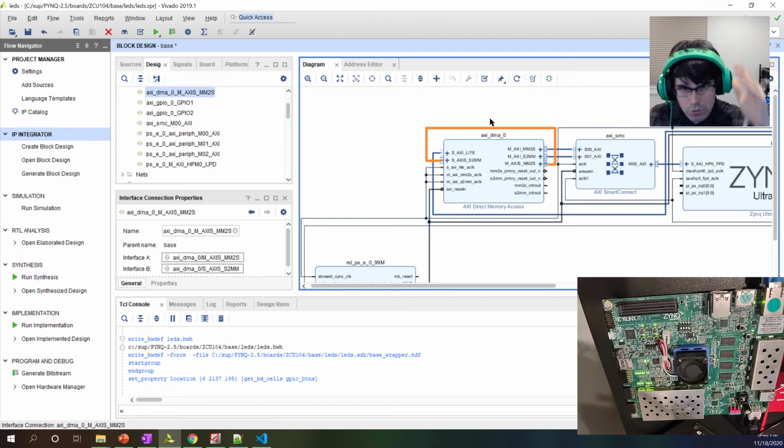And our goal is we're going to drop an HLS core right here. That's going to have an AXI stream in and an AXI stream out, and it's going to have an AXI-Light interface. Probably the first thing we're going to do is an adder, where we assign a static value, like a one, over AXI-Light, and then we add that value to all the values going through the stream. So we can show how we can do rapid addition, vector addition, or something like that to our array that we're going through the stream. And that will probably be our step for next time.